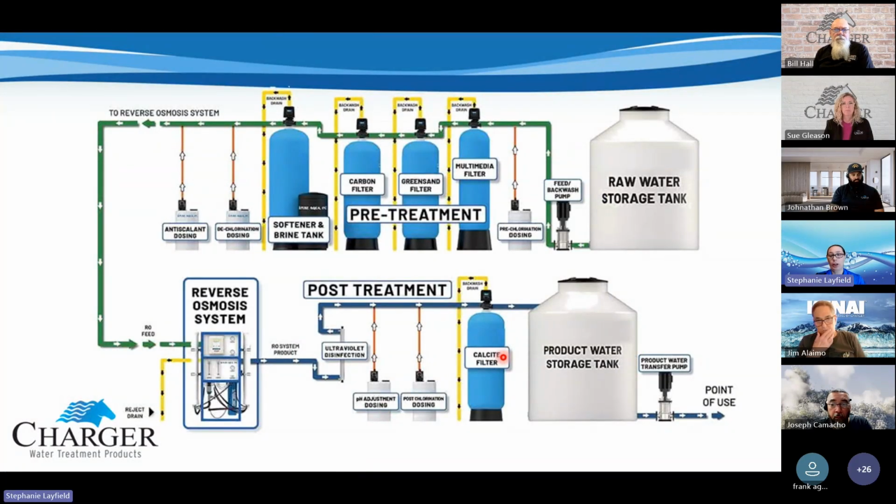You can also adjust the water chemistry afterwards. We have nice, clean water. We can turn it into whatever we want. One of the most difficult customers I've seen is actually Starbucks. If you have a large coffee shop, there is a very specific water chemistry that makes the perfect cup of coffee. And they want it consistent between all of their stores so that you experience the same taste no matter where you are. So they'll take it down to RO quality, and then they'll add in the exact mineral composition that they want for their coffee.